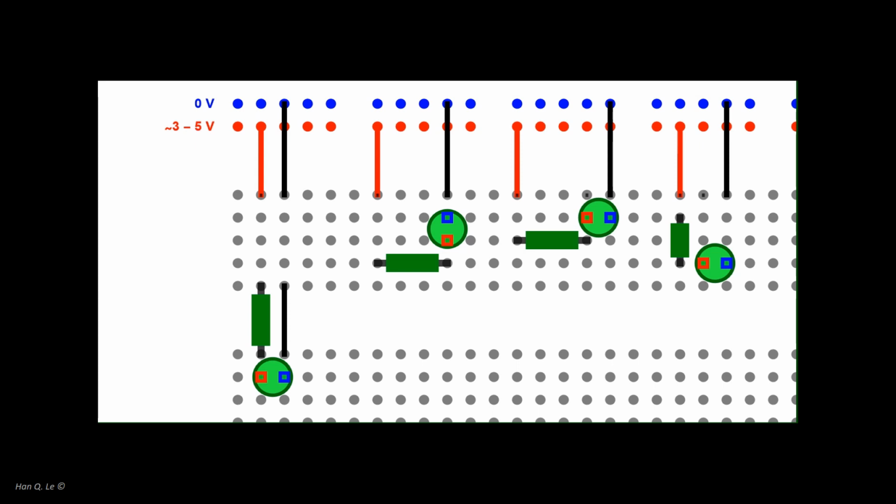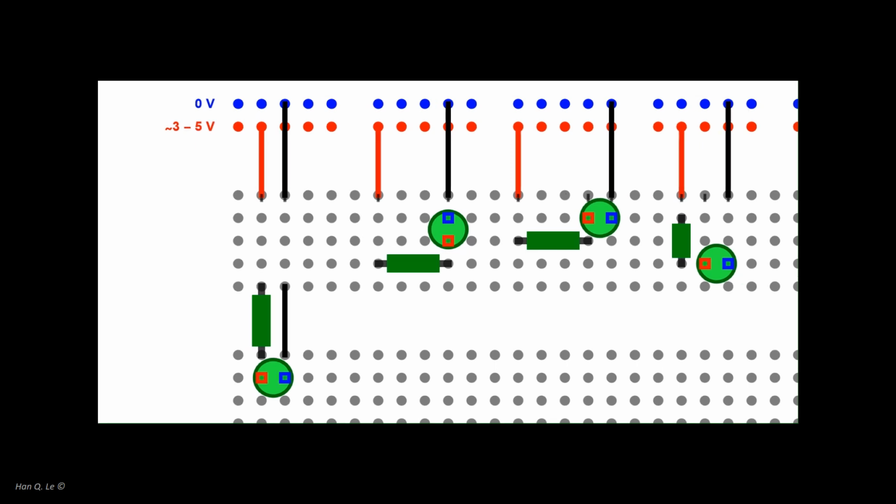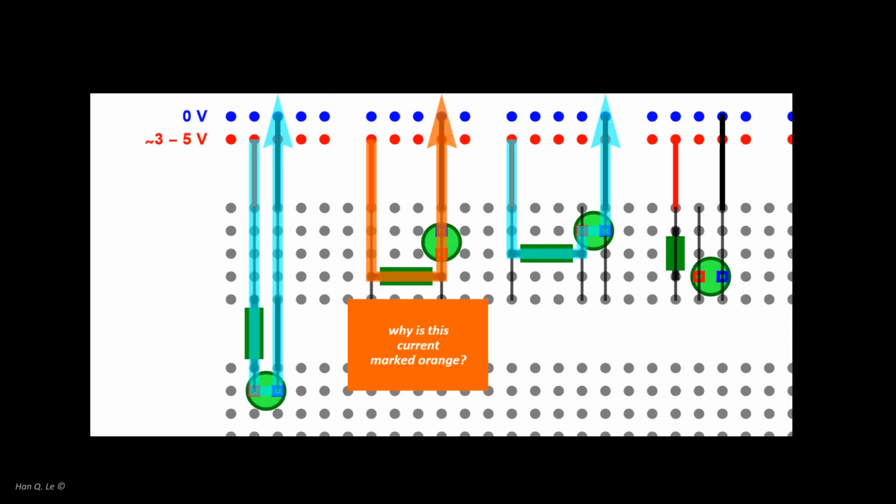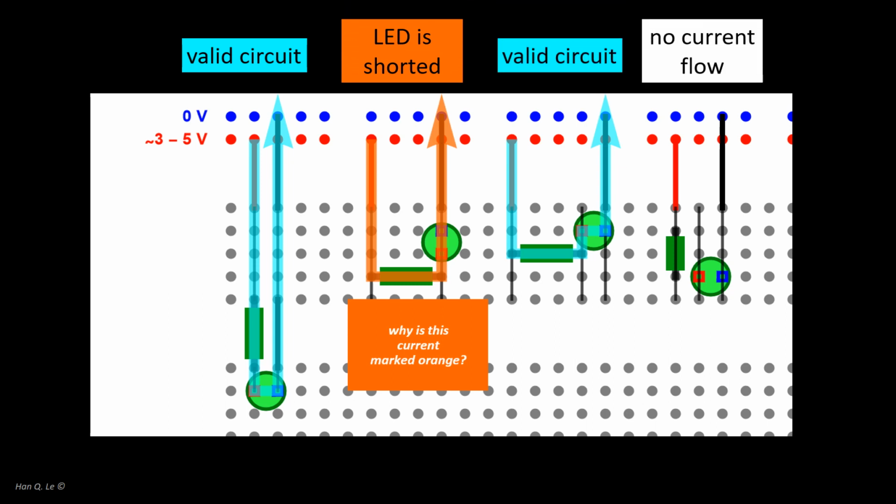Like previously, one can do a mental exercise: imagine lines drawn through all the relevant connected holes on the breadboard. Then, any circuit that has all the lines connected continuously will allow a current. As shown, there are 3 that allow current flow, as indicated with the highlighted arrows. But one is not what is intended, because the LED will not light up as both of its terminals are shorted. This is the same situation that was discussed in B3 above about an LED that will not light up. Thus, we can select one of the 2 that are valid, and build a circuit.